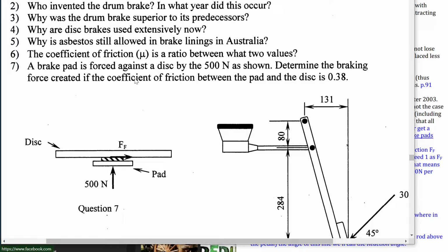There's also something to be mentioned: like the contracting band brake, it only worked in one direction, so that's another downside. Because cables only really can apply force in tension, when you start rolling the other way, the cable doesn't provide any tension.